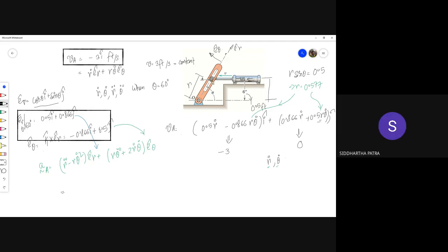The reason the acceleration is 0 is because A is moving with a constant velocity. So this right here is a 0. Yes, and you are correct. Whether I write it in Cartesian or polar coordinate system, it is 0. So I can directly write these two components to be 0. By the time you compare the quantities from velocity, you would know all the first derivatives: r dot, theta dot, r of course you know, and theta dot squared. All of these quantities would be known to you. So all you have to solve for is r double dot and theta double dot from two equations.